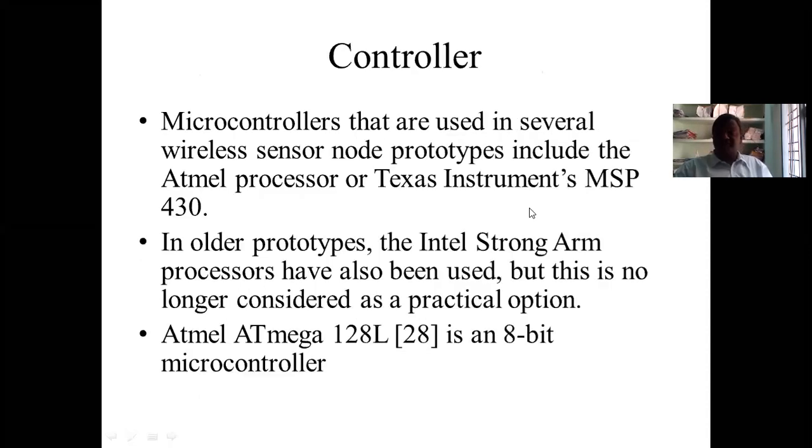Actually, sensors always work on low power. Once a node is connecting all the devices, we should manage the power, because four different types of devices are there. Sensors require low power, while the communication device requires higher power than the sensor. So how to manage the power? This power can be available either by battery or by solar energy, or both combined.